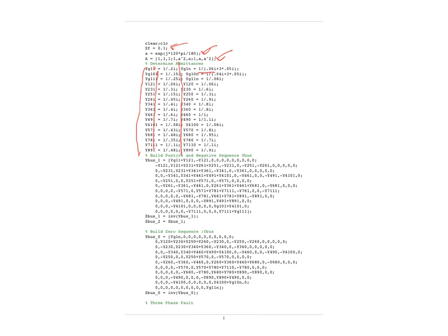And notice at bus 1 as well as bus 10, I added those admittances together, right? Those admittances were added together before they were inverted. The rest of them I just added as normal. But again, I denoted that it was a zero sequence except for the case where I had bus connections, and I showed them that way. And then this is positive and negative sequence Y bus, and then I invert it. And then I have my 0 sequence. And so you can go ahead and check those, but they should be consistent with the 2 tables that I provided earlier.